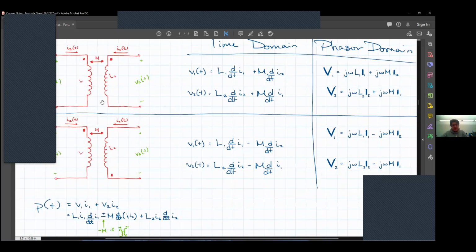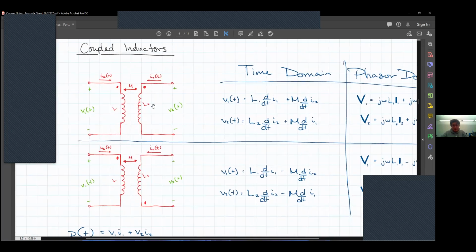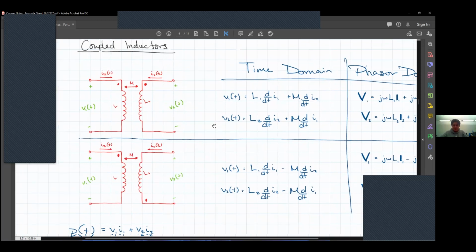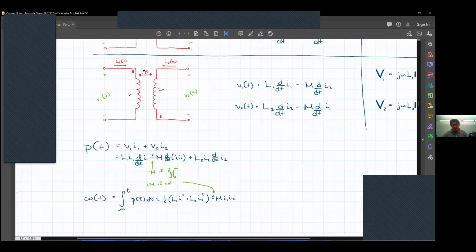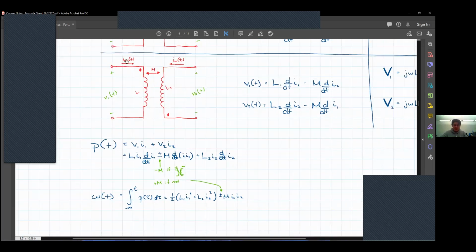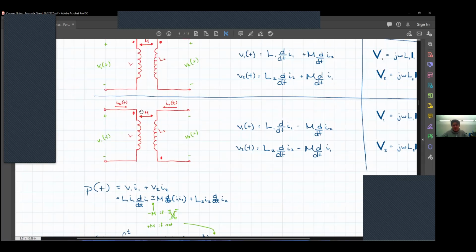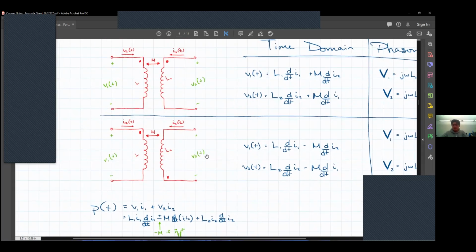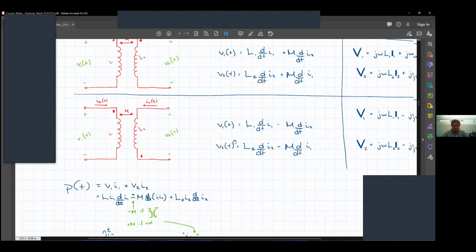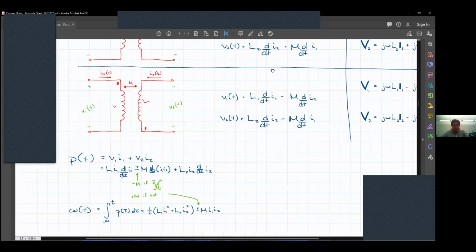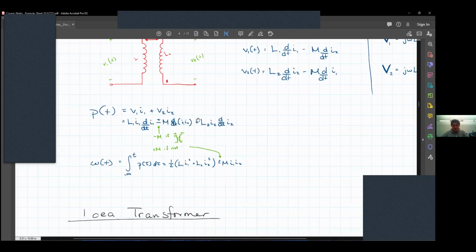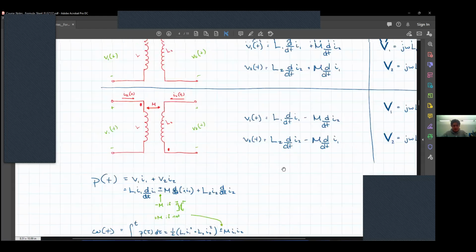And due to this, you can actually relate the inductance of both with how much voltage gets transferred between them and the currents that get caused by them. Do remember that it's important to note where the ends of each of them are, and by that, I mean what direction they're coiled in. So usually it's indicated by dots, and for the extent of this course, that's what you can represent them as. And you can get power values represented through the coupled inductors.